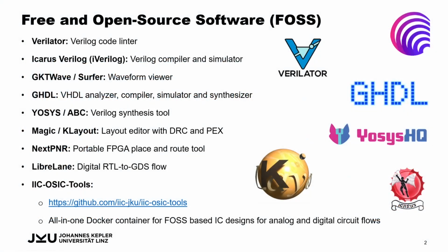So what are free and open source software, or FOSS, and what tools are available? In these next slides, we will focus on the digital flow only, so I will point out the most important digital flow open source tools. In this case, Verilator, a Verilog code linter, and Icarus Verilog, a Verilog compiler and simulator. Then we have waveform viewers, in particular GTKWave and Surfer.